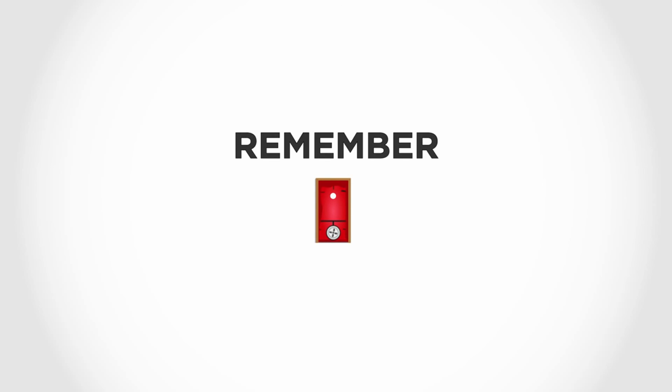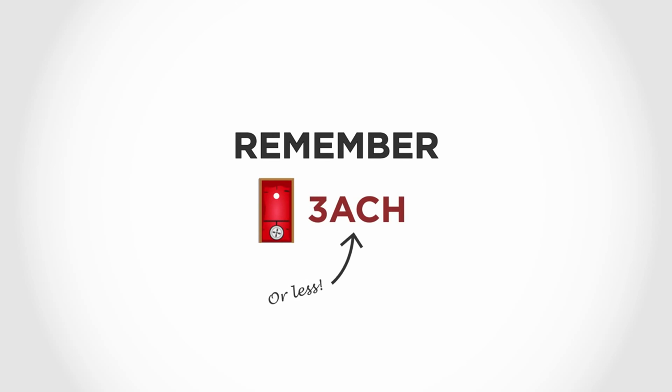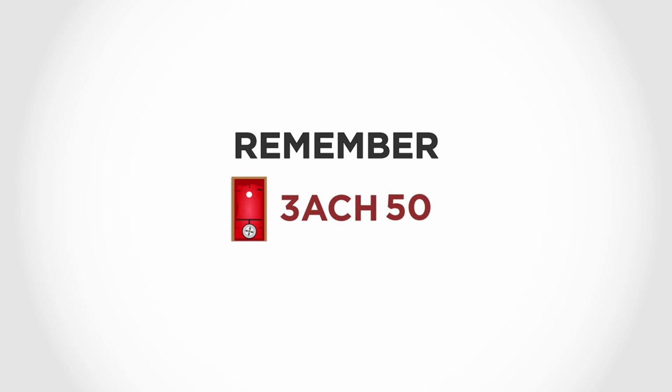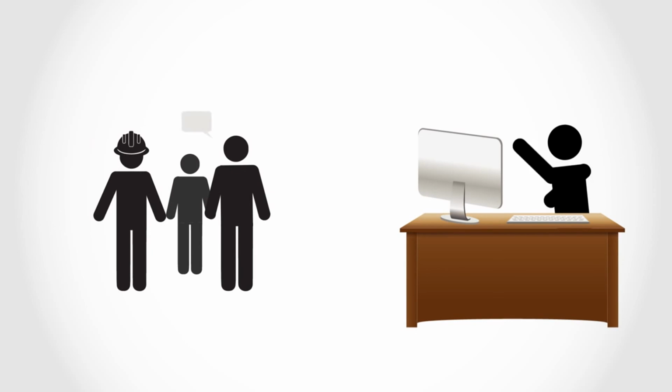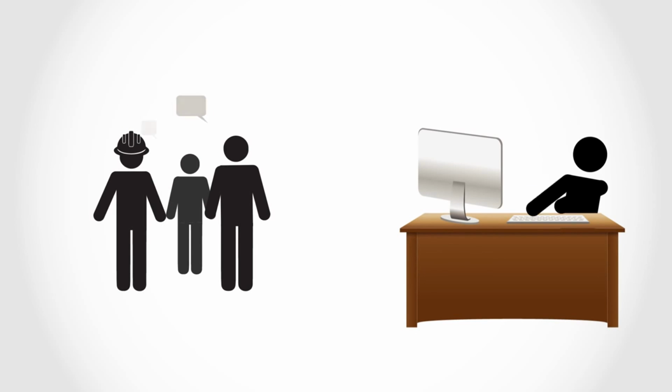So remember, New York State requires that newly constructed or renovated residential buildings must use a blower door test to demonstrate an air tightness of 3 air changes per hour or less at 50 pascals. There are 3 major organizations that train blower door testers. Checking their websites and asking colleagues for recommendations are good ways to find a qualified person to perform a blower door test.